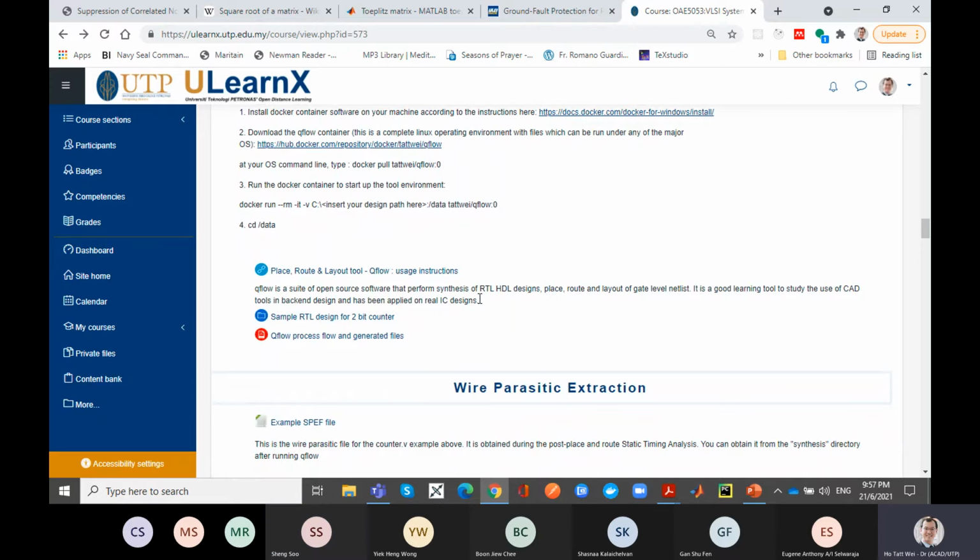Okay, the design rule check means that the tool is trying to do the routing and all that, and then it couldn't really converge 100%, and there are some rules that you had to violate. In a real chip design, like in your actual job, you have no choice. You have to go back and fix it and fix it and fix it until everything passes. And this is where most of your back-end designers, the layout engineers, have a lot of headache, because if the tool doesn't solve it, they have to go in and manually fix it.